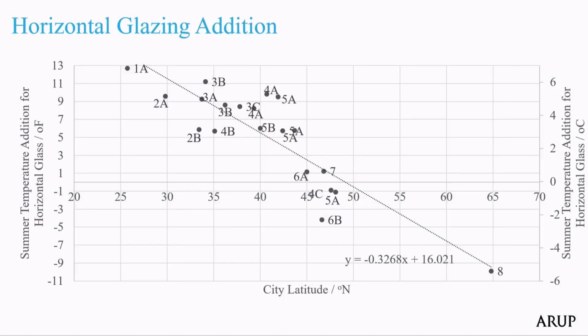Another interesting point to think about is the effect of the verticality of the glazing. In Munich, which is situated at roughly 45 degrees latitude, the effect of horizontal versus vertical is actually quite limited. It's essentially the same solar angle for both the horizontal and vertical piece of glass. But we ran all the analysis for both horizontal and vertical. So the results previously were for vertical glass, which is more common. And this is a plot for horizontal glass.